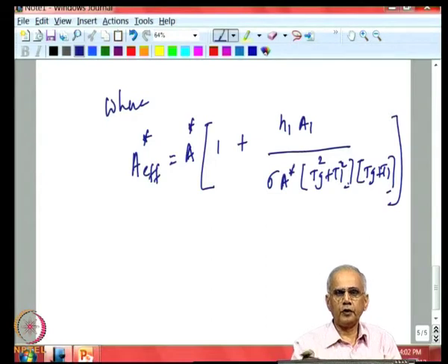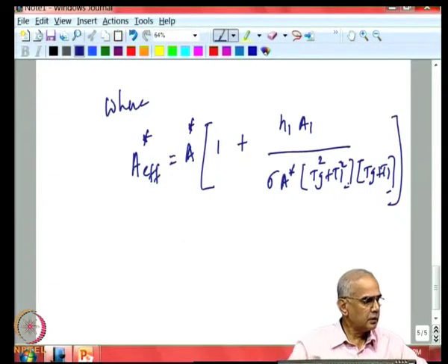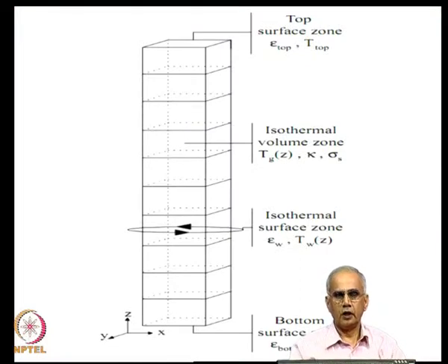So, this is similar to the way we took care of temperature gradient in the gas. These corrections for non-gray behavior of gas, for temperature gradient in the system, or for convection, can all be thought of as minor corrections to the 0 dimensional model. But of course, beyond a certain point, these corrections will not work. Now, let me take an example of a furnace. For example, take a long furnace like this. This is the direction in which furnace gases are moving.